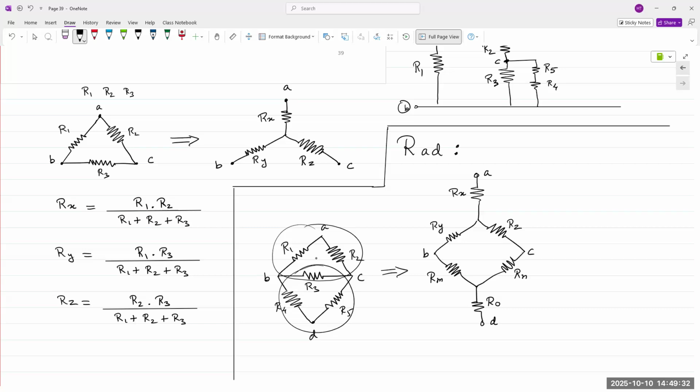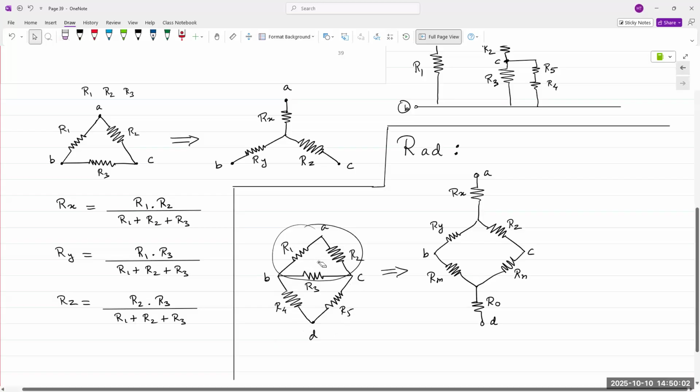And you can actually create this circuit in the lab. And you can find the values for resistors on both sides. Well, you don't even have to go to the lab. You know how to use LTSpice. You can do so in LTSpice also. Apply a voltage, 1 volt or 10 volts, to the circuit between A and D. The circuit on the left and circuit on the right. And look at the total current being supplied by your source. It will turn out to be the same. Okay.